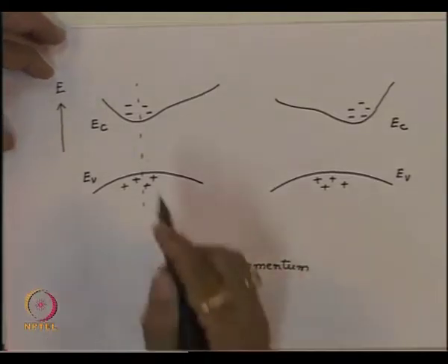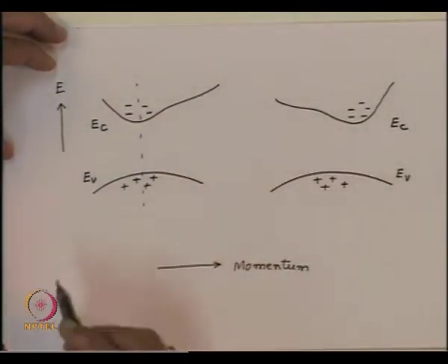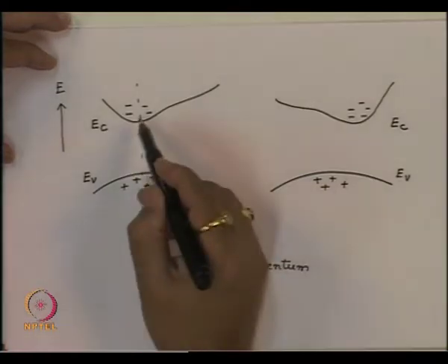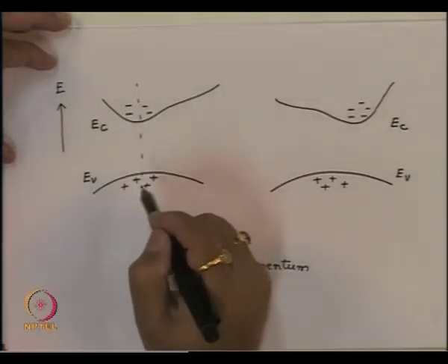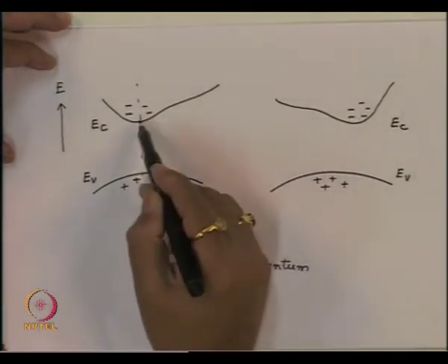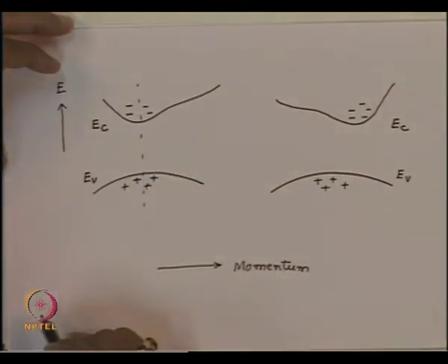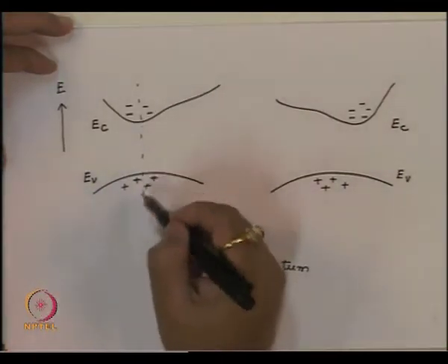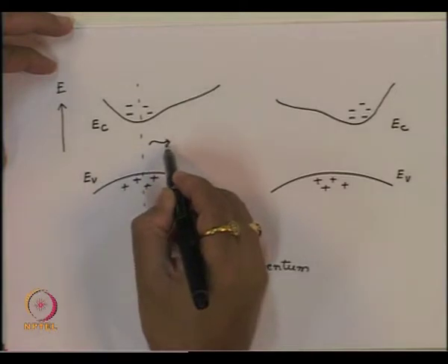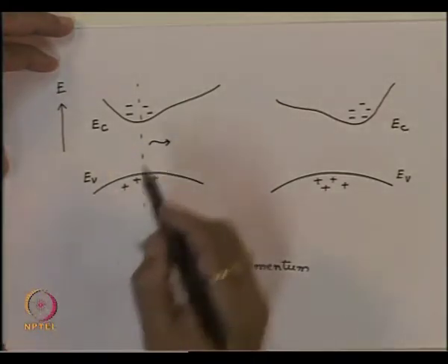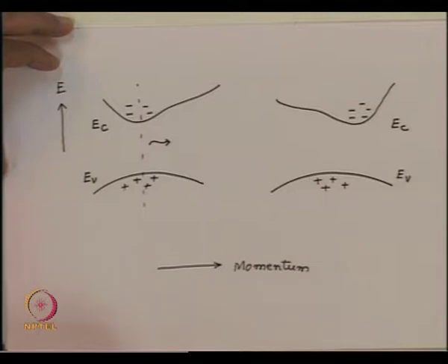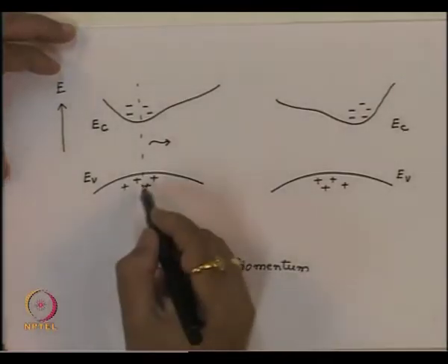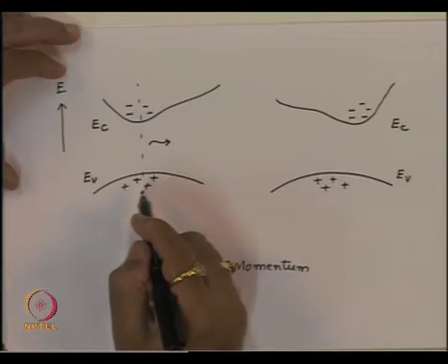Now, in this case, when the recombination of the electron and hole takes place, essentially only one process is involved, and that is the energy difference of these two carriers. So, these can combine and give you a corresponding photon of an energy equal to the difference of these two energies. This material is called the direct band gap material.